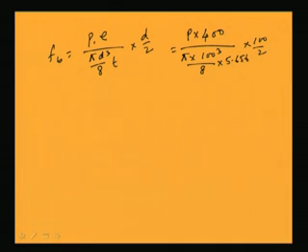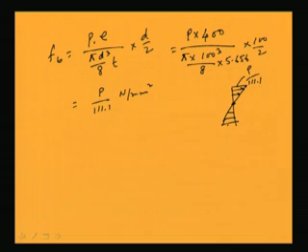After calculating this, we are going to get P by 111.1 Newton per millimeter square, and this stress will develop, as I told, if this is the center, then it will go on increasing towards the end, and this will be the maximum, which is P by 111.1. So, this can be found. Now, this stress will always be in the horizontal direction.